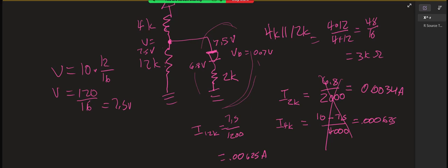Sorry. Okay, so everything is correct up to the R Thevenin. And then, well, I can't use voltage division. I said pretend like that's not there, but I don't know why I would. That's how you find V Thevenin, because you ignore the diode and use the open circuit. Right.